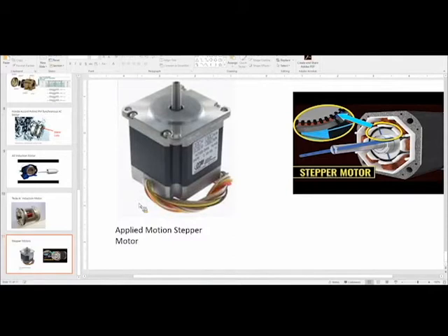What happens when coils A and B are energized together? The rotor will come to a position between these two cases, or it will move 15 degrees. After this, de-energize A. Then, after reaching B, energize C as well. This kind of operation is known as half-stepping.